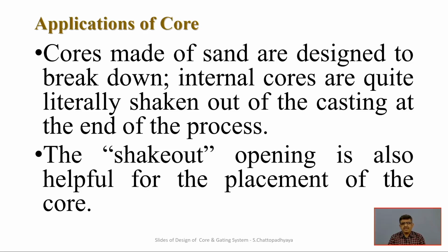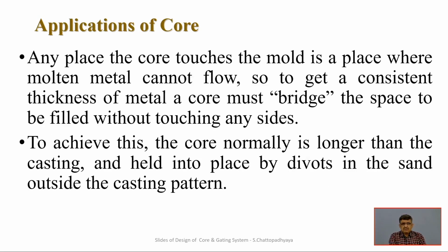This shakeout opening is also helpful for the placement of the core, because in the shakeout openings all those things, the overhanging pins, maybe chaplets, and other parts, will be put together for the placement of the core before casting. So in the next slides we will see exactly how the cores are displayed.